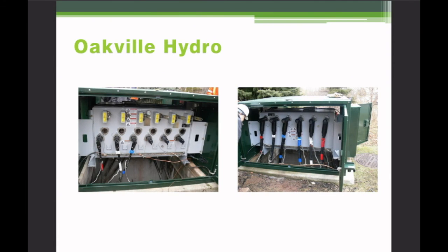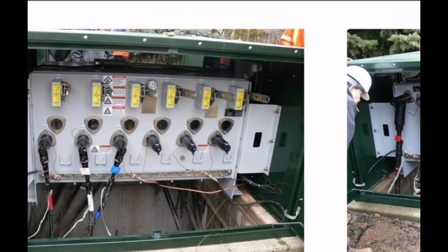We've got a piece of gas insulated switchgear, right? We can tell we've got gas insulated switchgear. We've got our viewing windows present. Our manual operating handles set up for single phase operation. If these were set up for gang operated, there would be a bar across them and a single handle. We also know we got our pressure gauge here. We're in the green, so this switch is ready to go. And we've got our parking stands for our bushings.